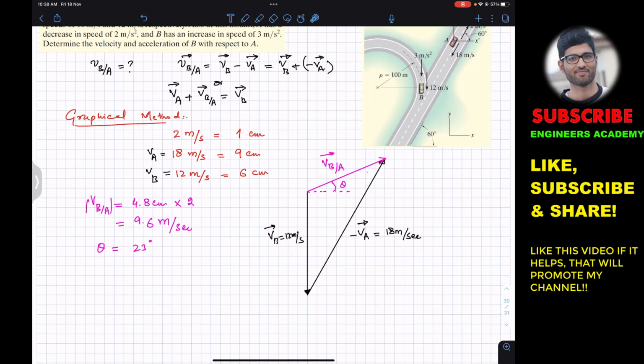Now we came up to this solution using this particular equation by subtracting VA vector from VB. So this is VB minus VA. We will get this as the resultant by head to tail rule. Now we can use this equation as well. According to this equation, VA plus VBA will be equal to VB. So this equation can solve our problem very easily.